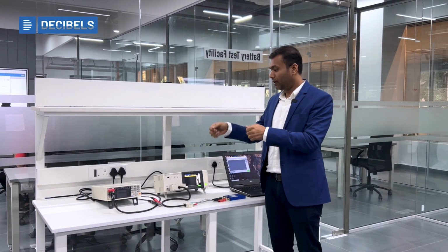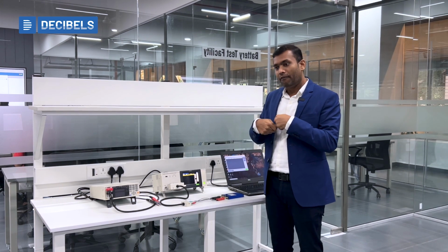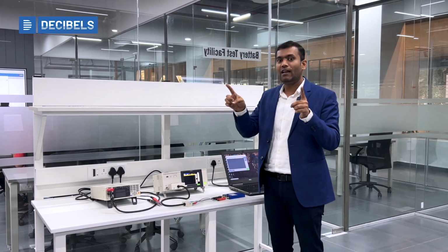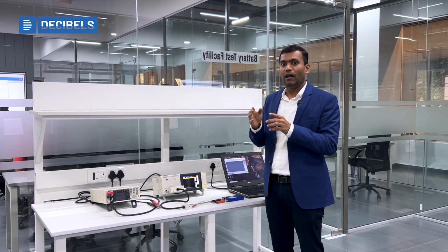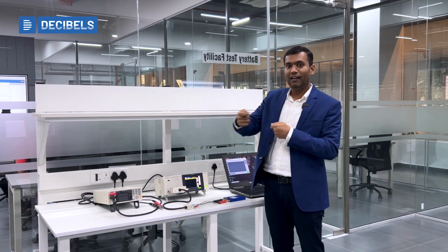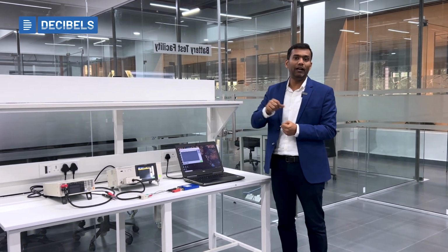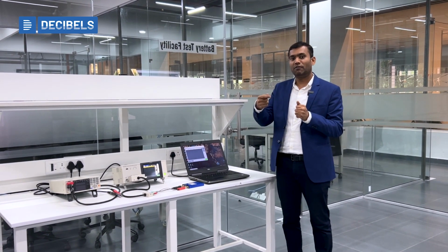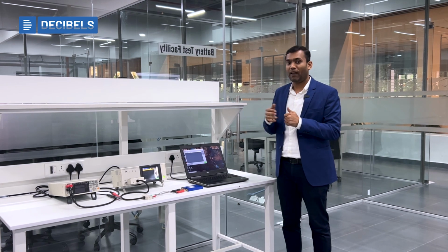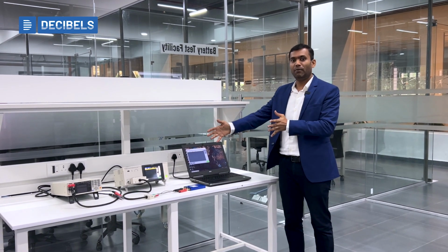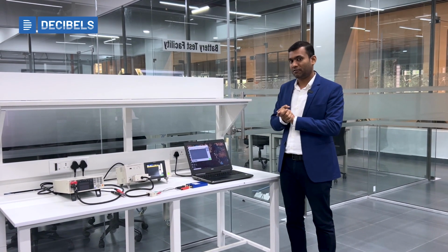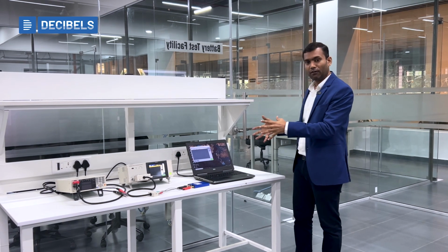By the end of the line, you want to test ACIR. You will get the ACIR impedance of every pack. If there is any variation in the manufacturing, or in the number of cells having different issues, you will easily identify the contribution of certain components to a failure of the battery pack, or you can reject the pack from the production line in the QC process.